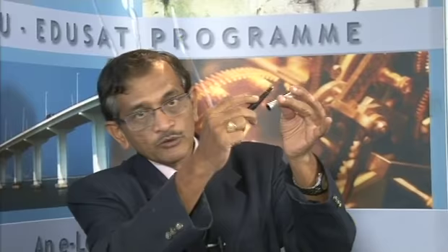Now we come to a very important concept called stream tube. You may be thinking, what is this tube? You know only the tube in a tire. A stream tube is made of streamlines. The walls are made of streamlines. For example, if you take this pen cap, it's a tube you can see here. So all these are having a streamline. All the boundaries are associated with a streamline having a different velocity. So if I define the boundary of many streamlines, note my point. If I define a boundary of many streamlines, that will form a stream tube.